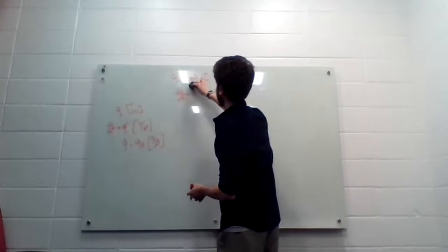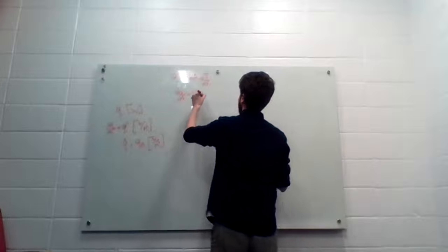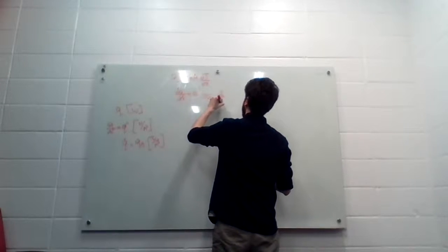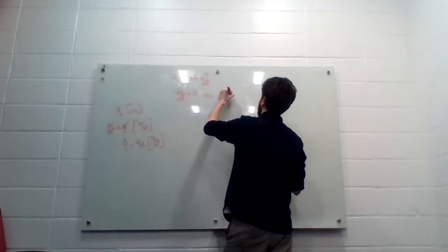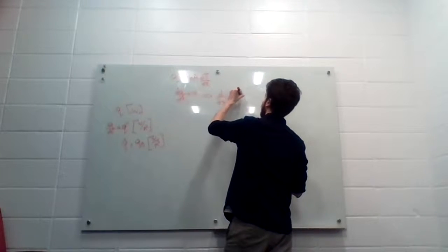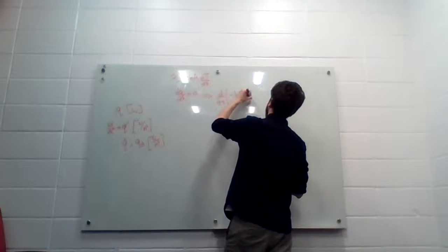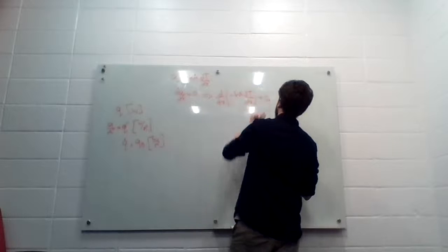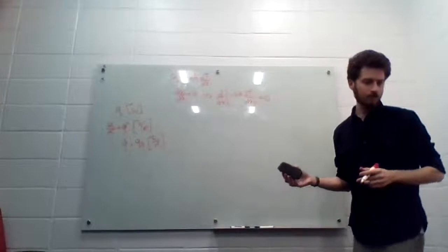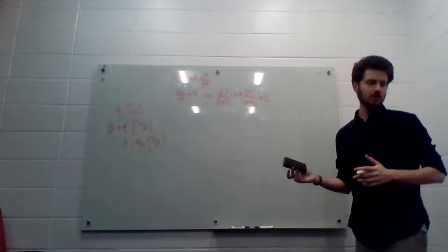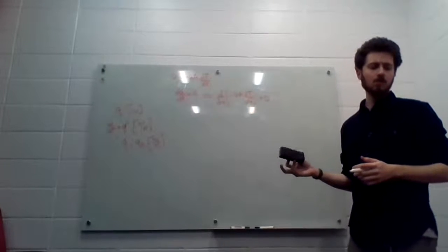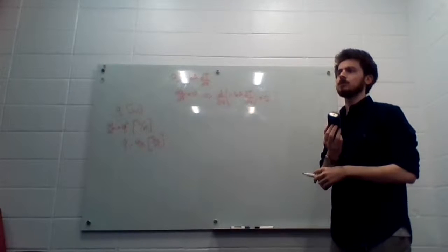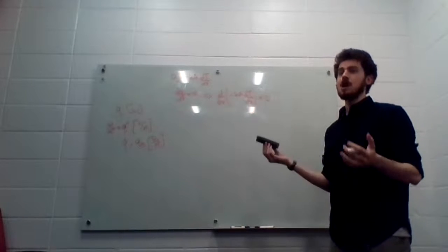Okay, so we're going to make a substitution here. So this second line becomes d dx of negative kA dT dx equals 0. By the way, just to back things up a little bit, what we're working towards right now is the heat diffusion equation, which gives you a description of how temperature changes with geometry.